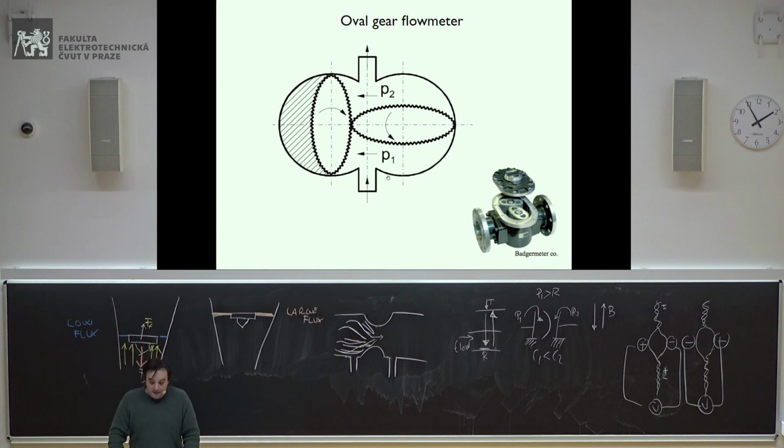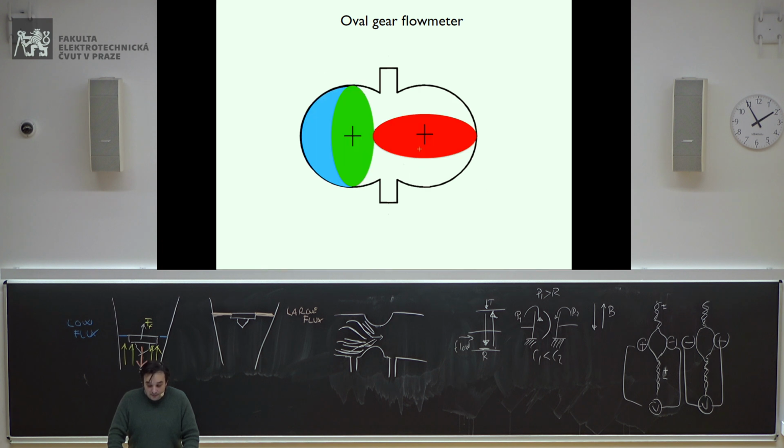How does it work? You have these two gears. Here in the photo probably you can see it better, which rotate, for instance, this one clockwise, and the second one, the horizontal one, counterclockwise. Okay? Now, how does it work? Let's say that you inject some water, and this green one rotates clockwise. So you are in this position, then it rotates. The red one rotates counterclockwise, until finally the water arrives on the top. And then, as you rotate again, the water will go out.